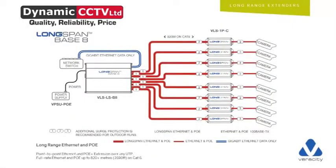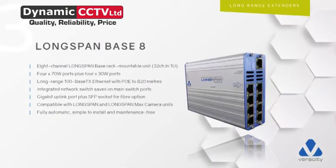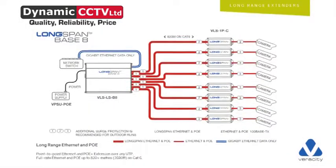For your cameras, and as you can see there on that diagram, which is very nicely done, I have to say, because it does explain it pretty well. You can have dual ports going back into that. You've got your 8 ports coming out, and don't forget you've got 4 ports at 70 watts, and then you've got your 4 ports at 30 watts. And so you don't put one of these in the middle of a building somewhere where you need high wattage, PTZs on corners of buildings and things.